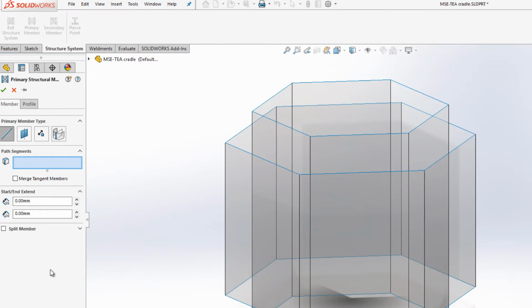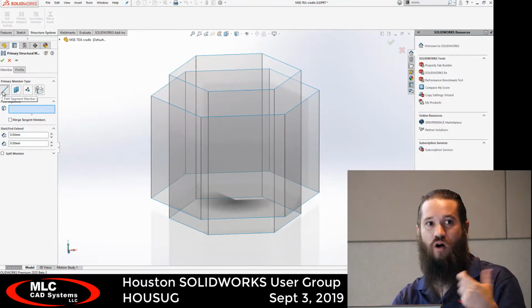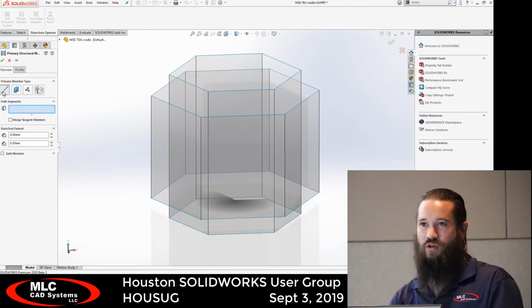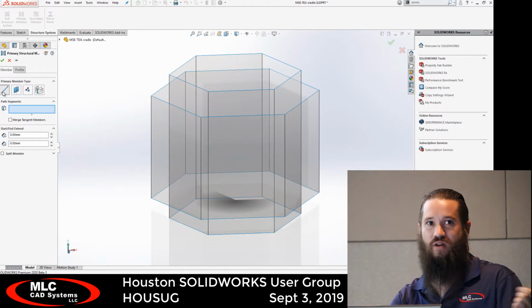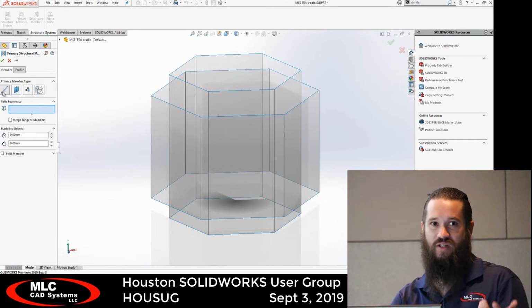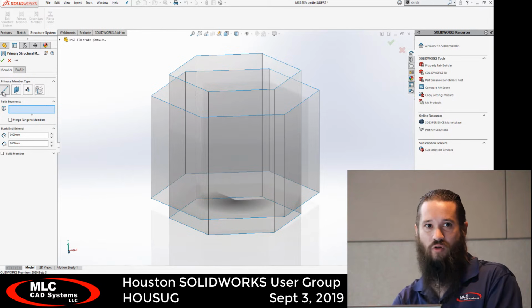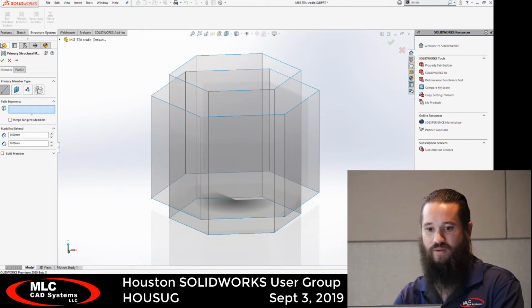And the way that we define these, again, I have surfaces here, is you can either do point or length members, which is normal sketches, right? Or edges of surfaces. That'll also be recognized without having to sketch each individual line, right? So remember that little trick that I was showing a second ago where you extrude it with a normal solid, then delete it? That's kind of like what it's doing here, only instead of a boss extrude, they're doing a surface extrude. So that's a good way to think of it.